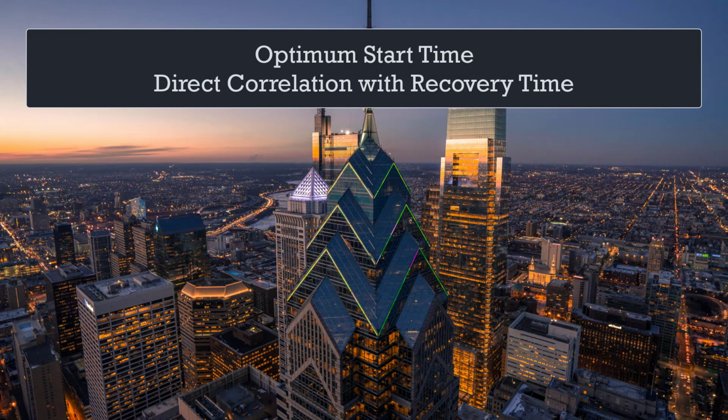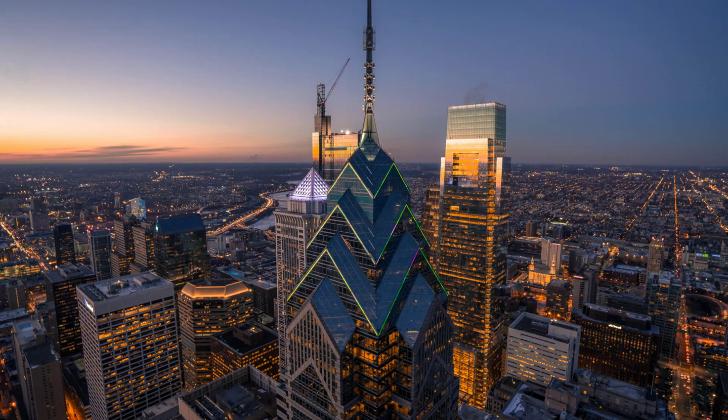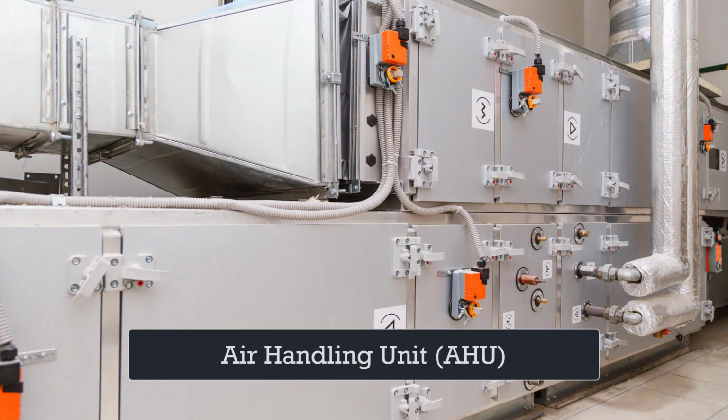Optimum start time is directly correlated with recovery time, the time required for the building's HVAC system to remove internal heat during the cooling mode or to add heat during the heating mode. Facility managers having a basic understanding of building thermal recovery concepts are better equipped to ensure that BAS enables an optimum HVAC start time. While some building operators consider shutting down HVAC equipment prior to the end of the lease-defined occupied period, generally described as coasting, there is less energy reduction opportunities in implementing optimum stop time at most facilities. Operation of HVAC systems through the entire lease-defined service period is primarily driven by a fresh air requirement provided by the building's air handling equipment.